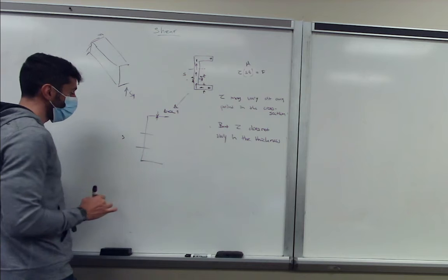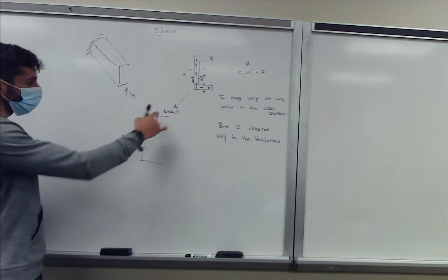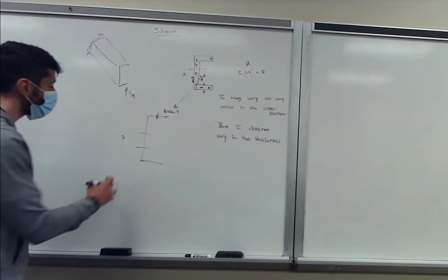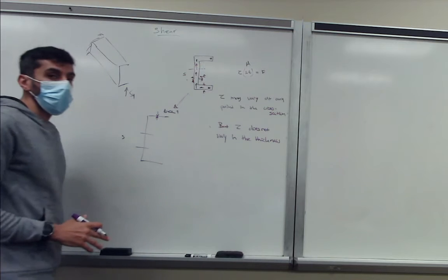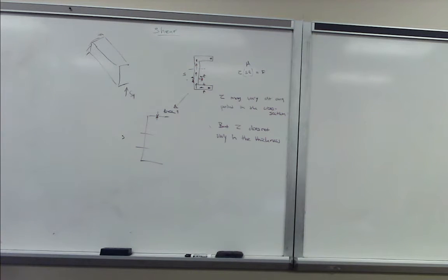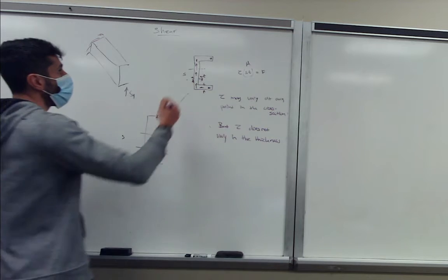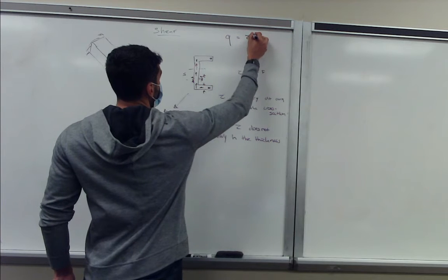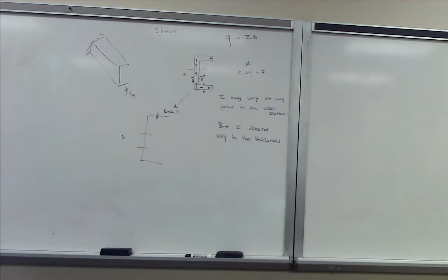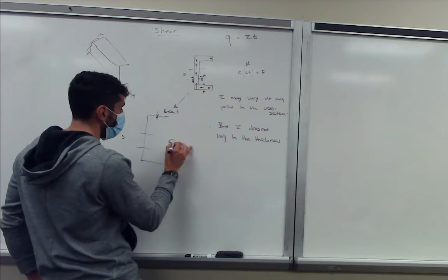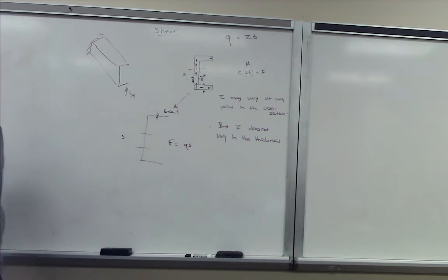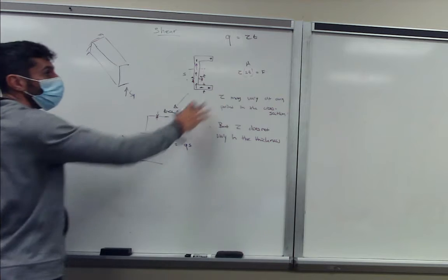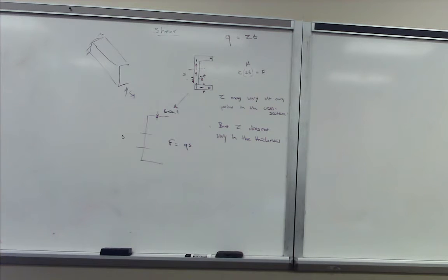So if I have my segment S and my thickness T, which I can neglect, how do I get my area? Instead of looking at shear stresses, we look at a different concept, shear flow. We identify shear flow as q, and say that it's equal to the shear stress times T. In this way, we can say that the force is equal to the shear flow times the segment we travel over. By assuming that the shear flow is equal to the shear stress times T, we have to take into account the area.